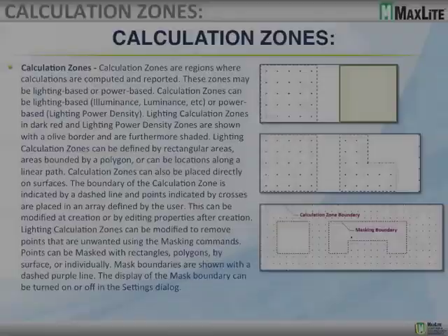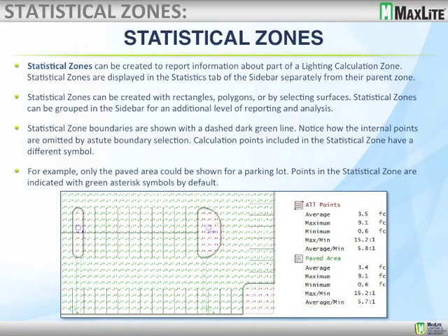Very good. Thank you for clearing that up. Now, a statistical zone is, as you mentioned, a specific zone where there's a focus. And I have noticed that these days they're asking more and more about the minimum, the maximum, the min-to-max ratio, and the average-to-minimum ratio. Can you share with us why that's important to the user? Well, not only important to the user, but important to the city, county, townships, what have you, whoever you have to send your lighting layout or design to. You have to meet certain criteria for certain locations. So is that a national code, or are there local codes for such things?